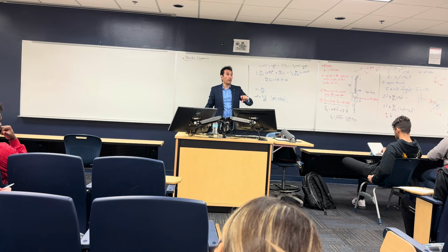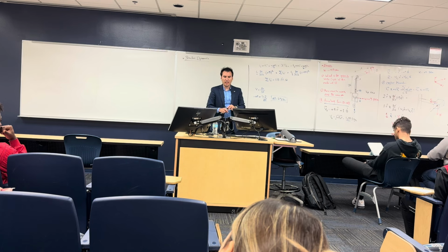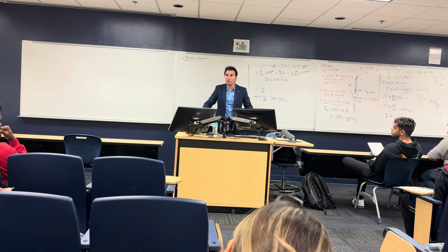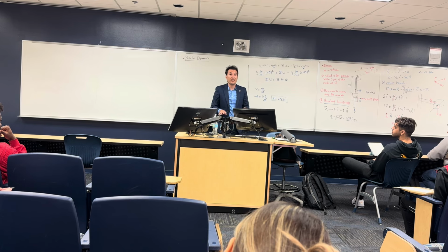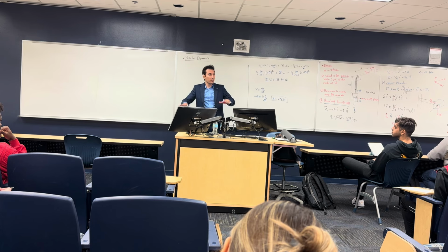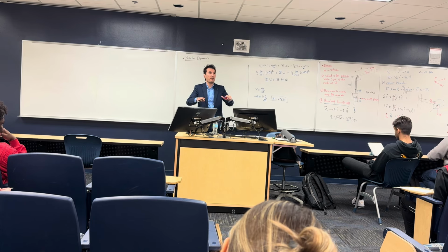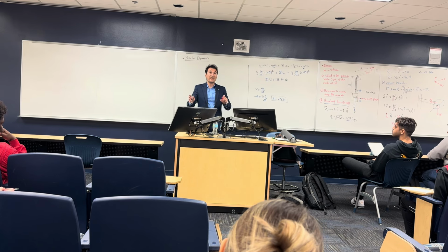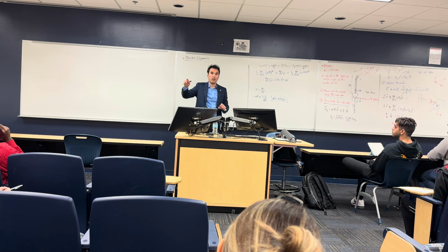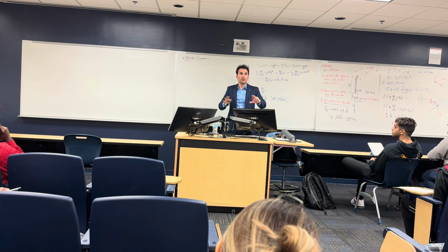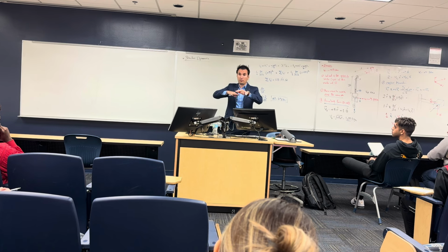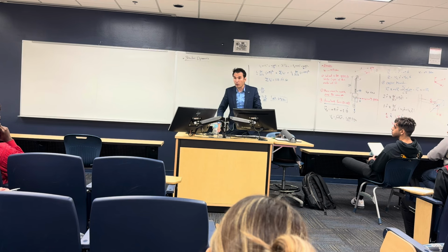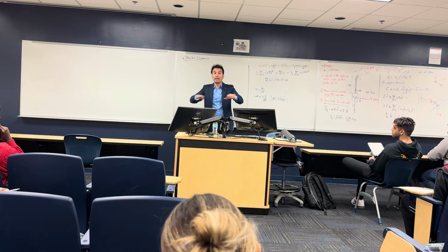What else do we call failure? Let's say I'm moving like this on my floor, and you over there feel that the floor is moving or shaking. We call this serviceability. It didn't fail, but it makes a displacement that everyone feels and makes us uncomfortable. That's why the standards on structures limit what we call the maximum deflection. We design this floor to make sure that with the live loads, the loads of the chairs and desks, and the dead loads like the flooring and the body itself, it is not going to fail.